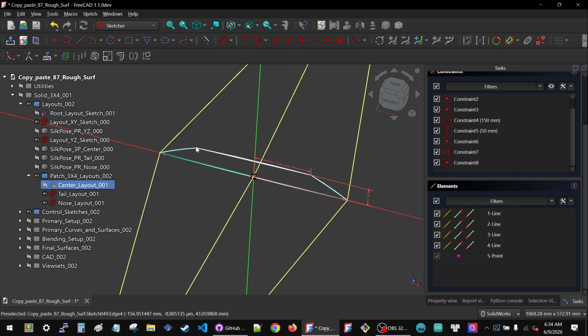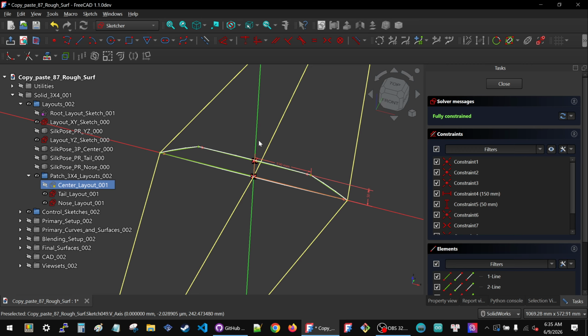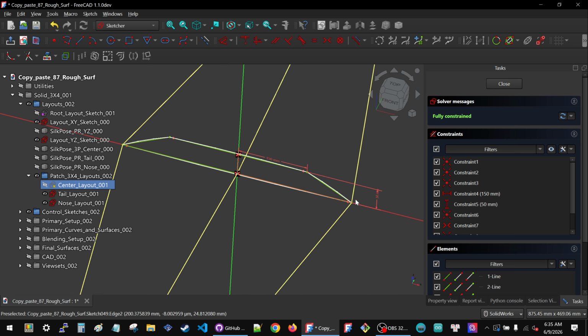and then I'm going to make this point here, and this point here symmetric with this axis. Thinking about it, okay, I did it. The sketch is fully constrained. Now all I want to do is adjust the lateral position of the rail, right? I'm going to want to make the deck bigger, the rail smaller. So this is 150, and if I remember correctly, this would be 250 because the overall width was 500.